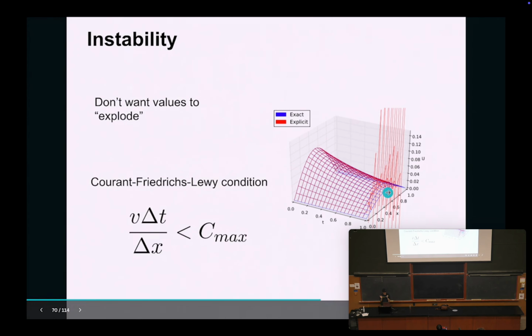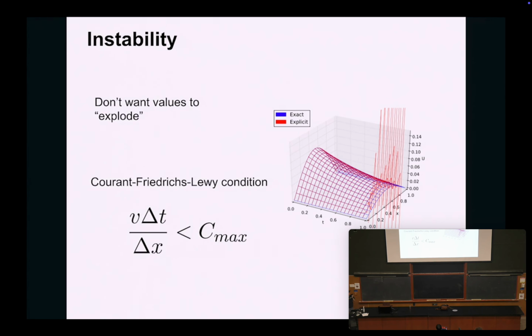Okay, instability. When we truncated our expression from earlier, we introduced some errors into our code. It's not going to be super accurate. As you can see on the right here, things start to explode when we don't want it to. To avoid that, the most fundamental condition that should be met is this bottom left.